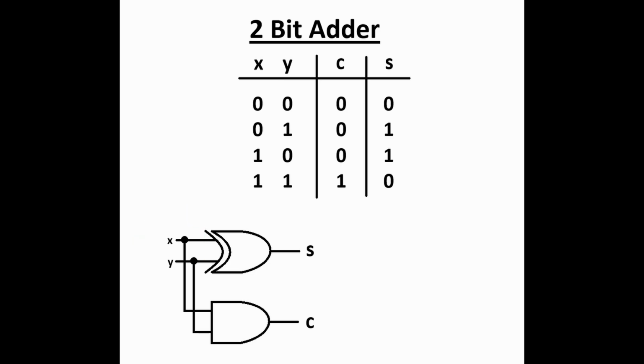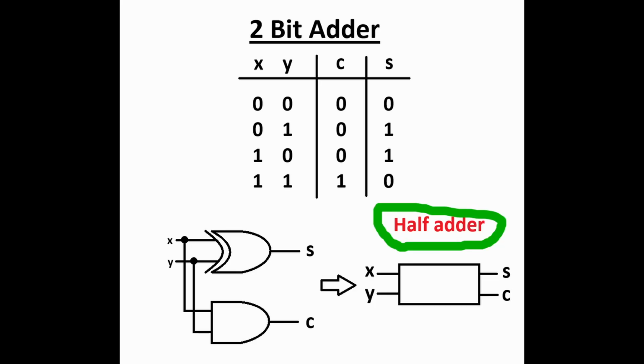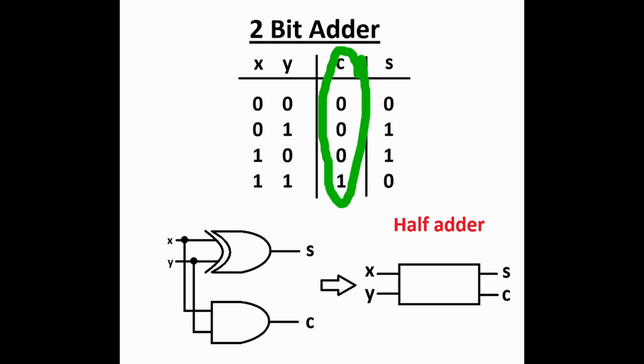This simple bit adder with carry out is called a half adder. Why is it called a half adder? Even though we've accounted for an overflow from our sum using a carry out output, notice that we haven't included a way to carry in an overflow from another adder into this one. This is a necessary capability for more complex calculation circuitry.